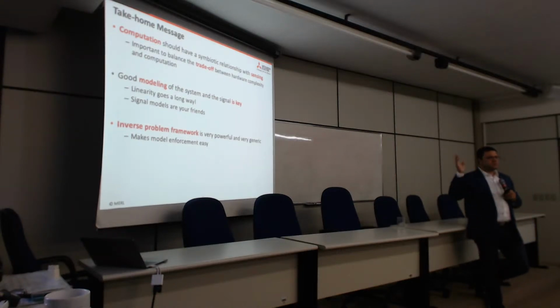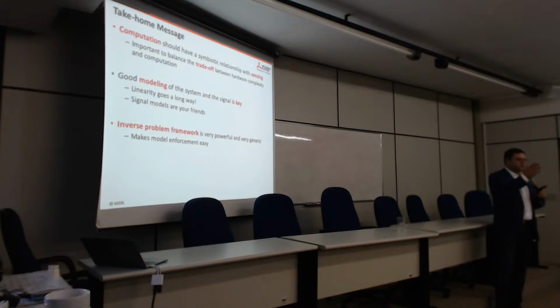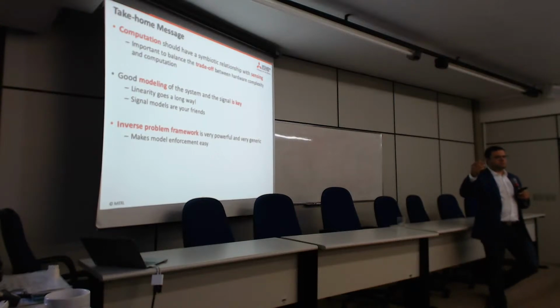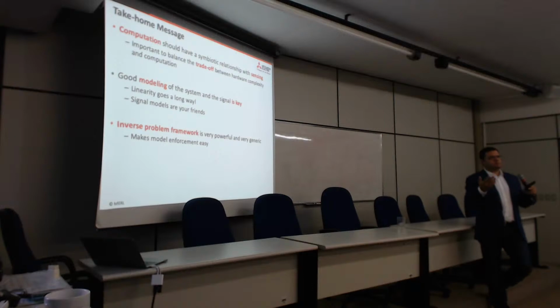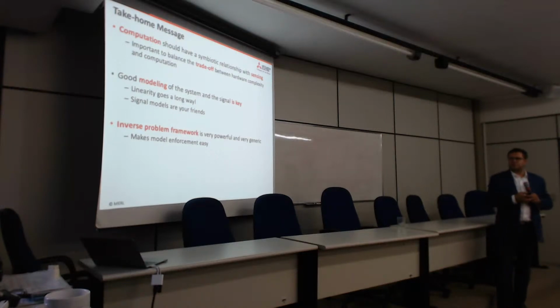And the other thing to know is that linearity can go a long way. A lot of the time, you see systems that look very nonlinear, but with very simple transformations and sometimes a small expansion in dimensions, you can convert them to linear. This is something we did with LiDAR. LiDAR will typically give you intensity and depth. Well, we made it a 3D scene. That's a big expansion in size, but it makes the model linear. With our timing errors, we just moved convolution to the other side, and we converted the delay again to an impulse. That was a small expansion in size, but it makes the problem linear.